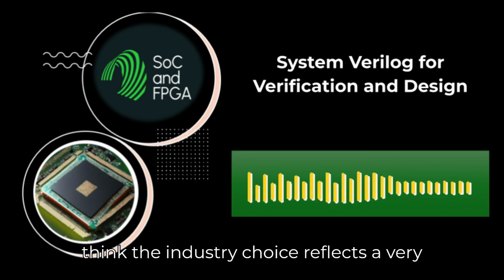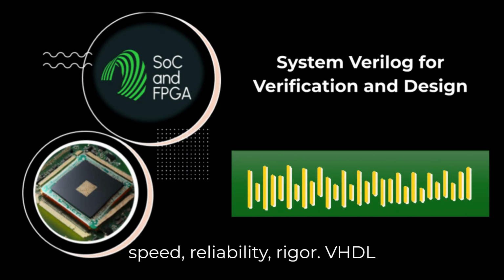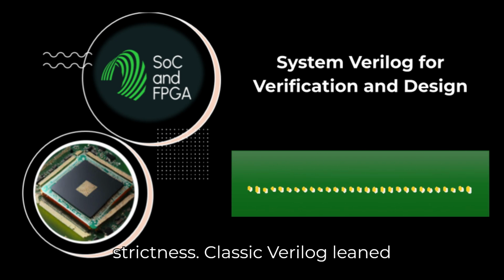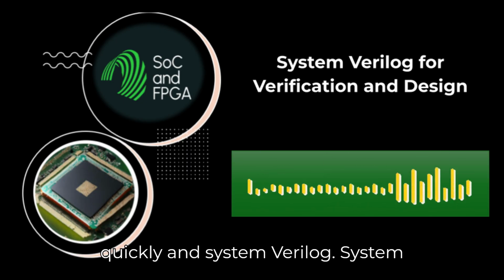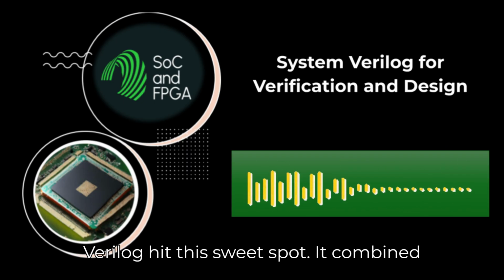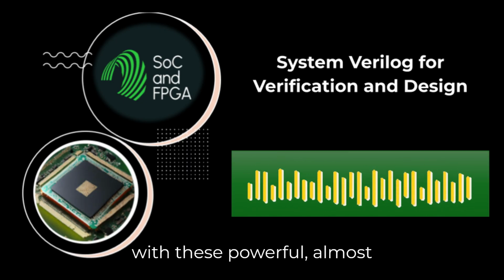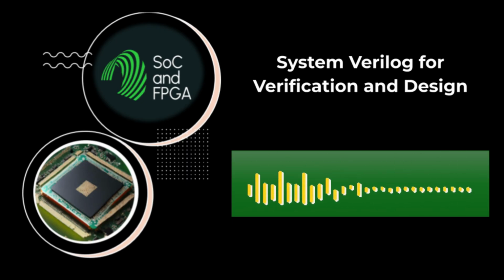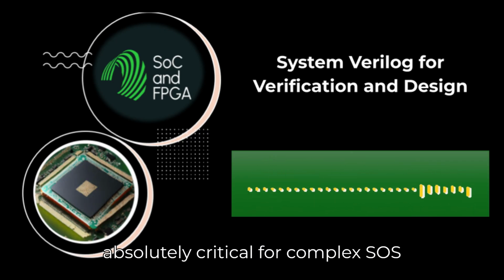Well, I think the industry choice reflects a very pragmatic balance, right? You've got speed, reliability, rigor. VHDL prioritizes error prevention through its strictness. Classic Verilog leaned towards ease of use, getting designs down quickly. And SystemVerilog? SystemVerilog hit this sweet spot. It combined Verilog's relative design simplicity with these powerful, almost software-like features for verification. And that verification capability became absolutely critical for complex SoC development.